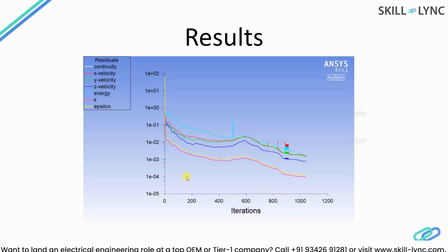So as far as results, before we jump and run the simulation, I wanted to show you a sneak peek of what you can expect. Here you can see the governing equations that you're solving: the continuity equation for mass balance, XYZ velocity, which is nothing but the XYZ momentum conservation equations, energy, one equation for turbulent kinetic energy and one equation for turbulent dissipation.